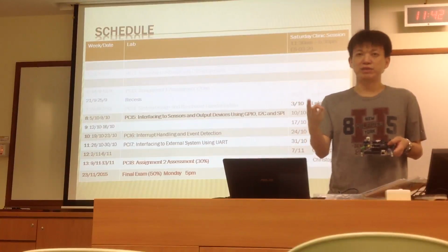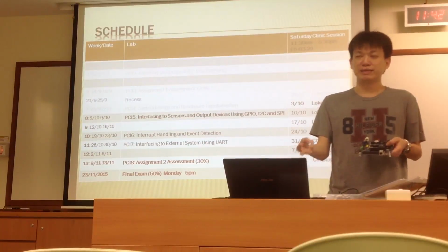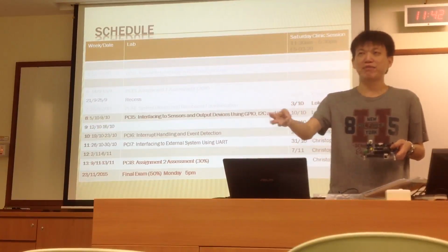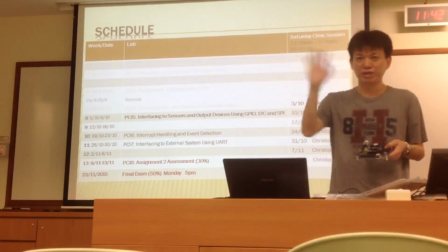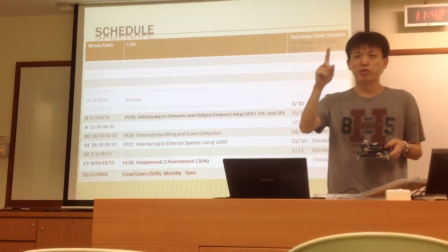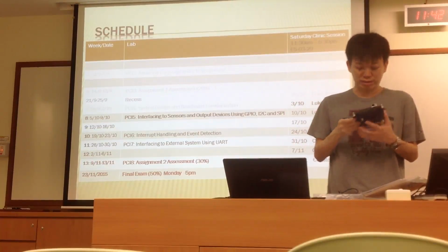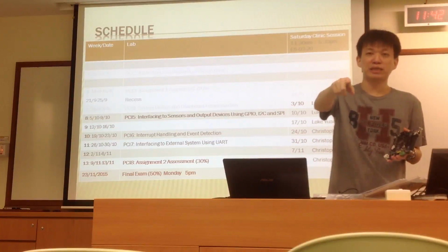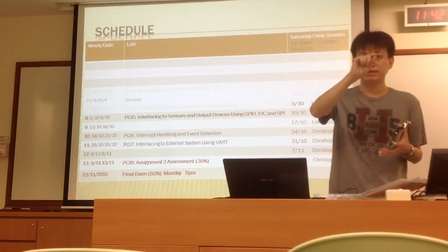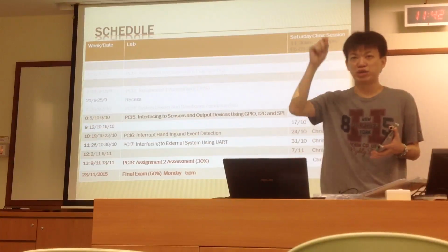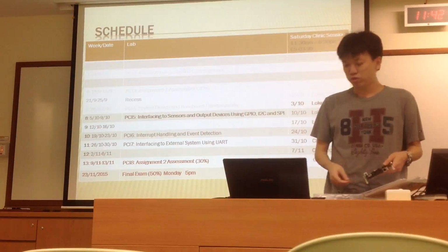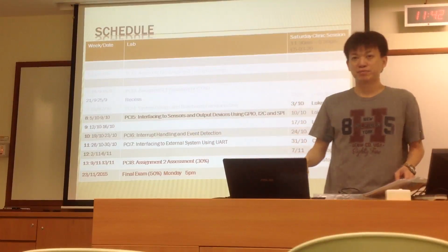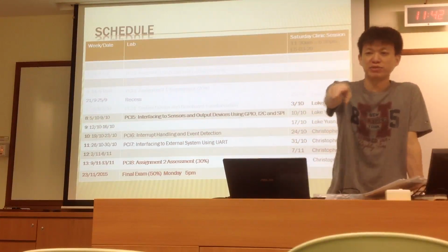Open drain, you set it equal to 0. That's implied. You didn't set anything, that default is 0. That means it's not open drain. If equal to 1, it means open drain. Like I2C. In I2C, the SCL and SDA, these 2 bars are open drain. So normally we need to connect some pull-up resistor there. I think it's in the notes.